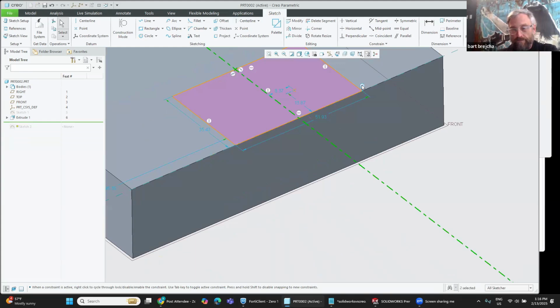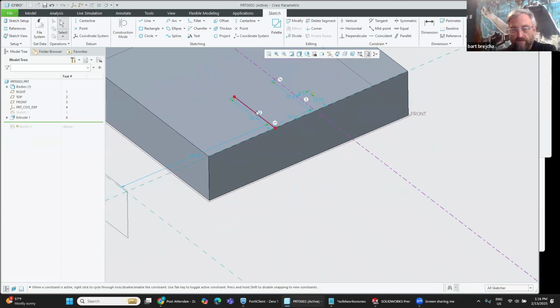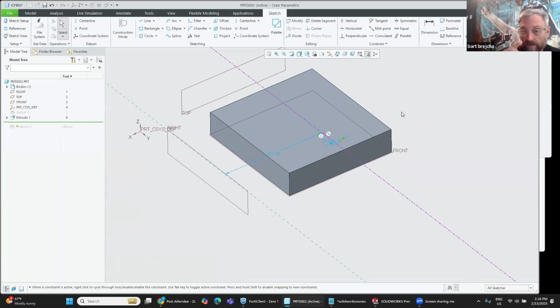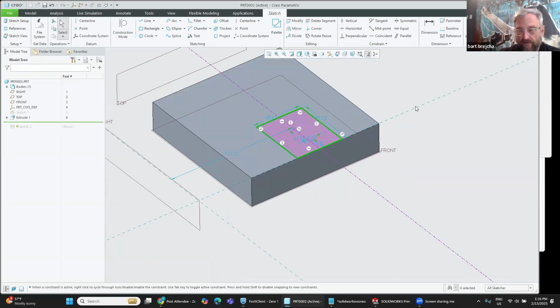I'm going to basically delete this box for a second just to slam it back down onto the table here. So I've got a reference here that I'm going to delete. SolidWorks has a button in it that says automatically create references, but it works about 30% of the time. It's consistent in how it works, so it seems intentional, right? So I'm picking here, and it fetched this edge automatically.